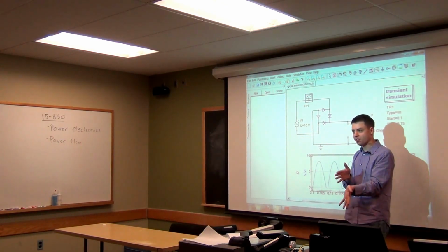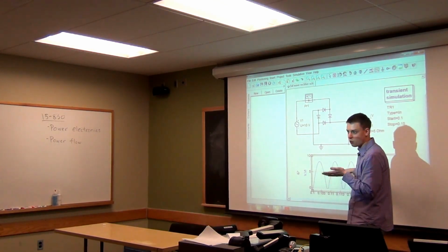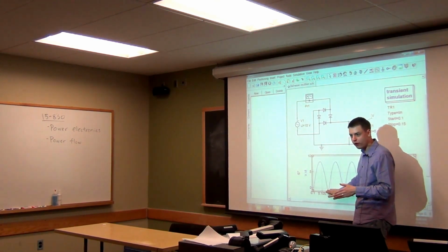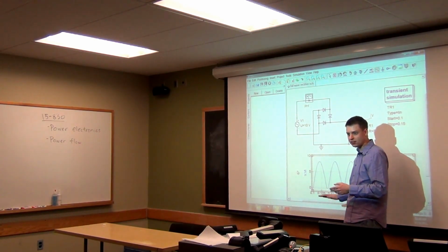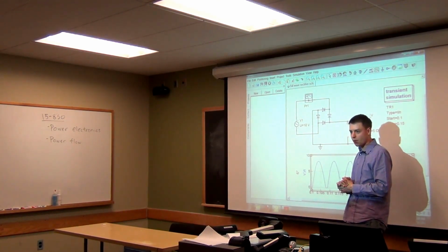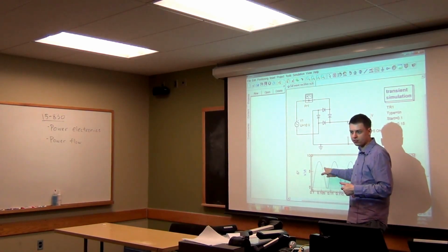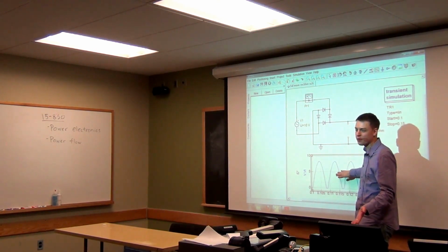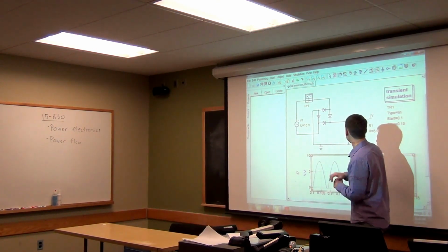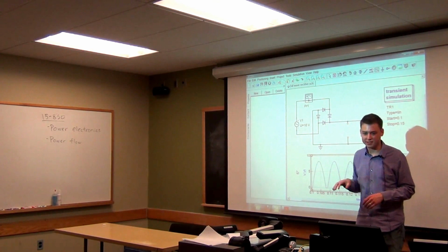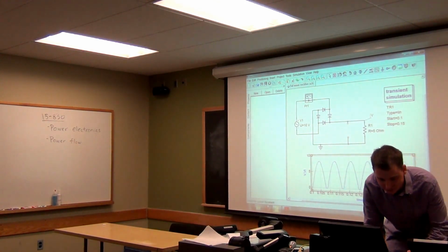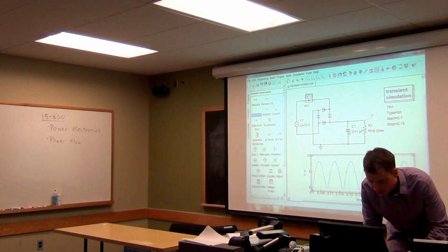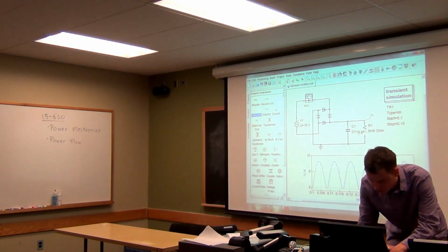Now, when we don't have the capacitor, we get something like this still. So this is kind of better than the half-wave rectifier, because the half-wave rectifier just had this as 0 here. So we weren't using that electricity at all. But we still probably wouldn't want to feed this signal into an electrical device, right? This is still not very well tempered to basically provide a constant voltage to that system. So let's add our capacitor again. I think I was doing it 10 millifarads again.